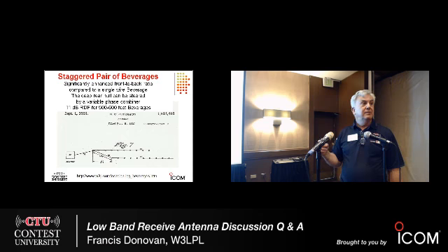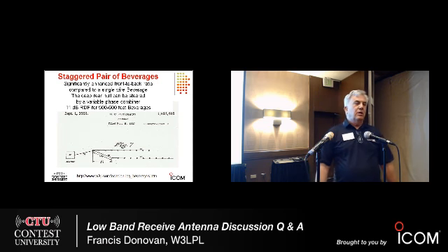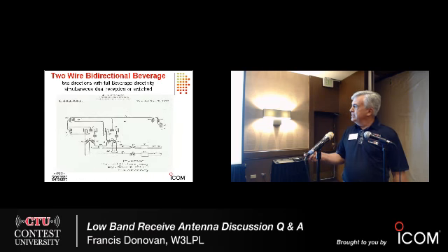Right. These are close together though, right? It's in black. They're within a foot of each other or something. They have to be able to operate as a transmission line. The way these antennas work is in one direction the two wires are in phase, so they operate as if they were a single wire. So in that case the spacing doesn't matter.